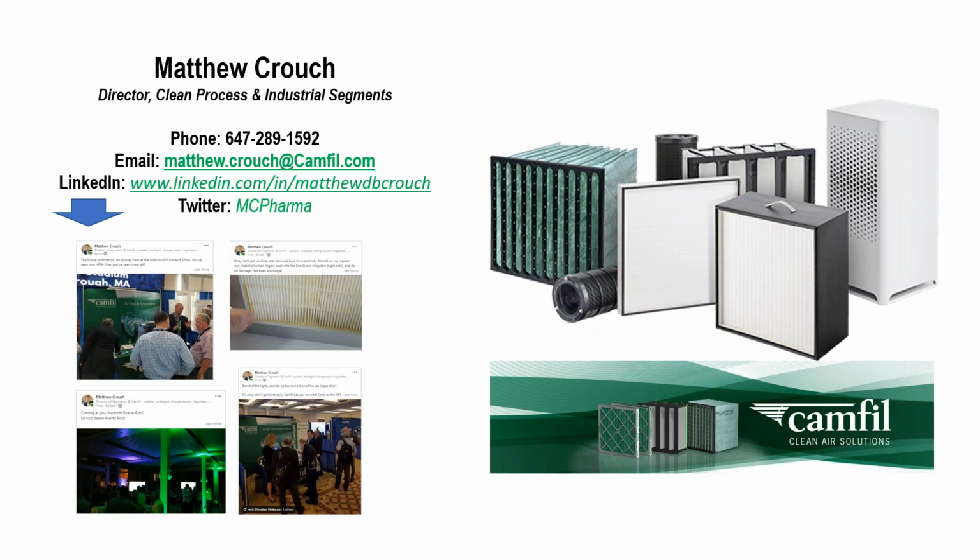Matthew, I had a question actually related to EnerGuard and the new filter media. Can it be used in existing housings, or does it require new housings? That's a good question. So the new medias, be it EnerGuard or PTFE, can be utilized within existing housings. There's no reason to change that. The only thing that you really have to be careful of is to make sure that the filter sizes are compatible. So as long as the sizing is compatible, they're interchangeable between housings.